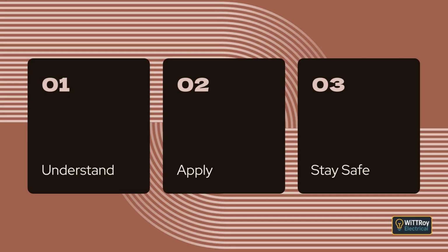Clause 3.11.2 Classification of wiring systems. Underground wiring systems are grouped into 3 categories. The category depends on the type of cable and the amount of enclosure or mechanical protection provided. A Category A system is considered inherently suitable for below-ground installation and generally does not need extra mechanical protection.